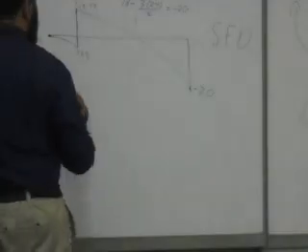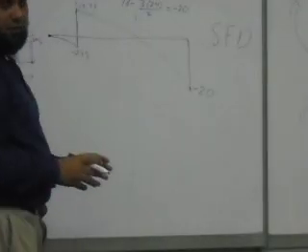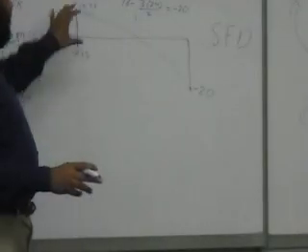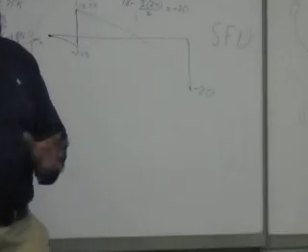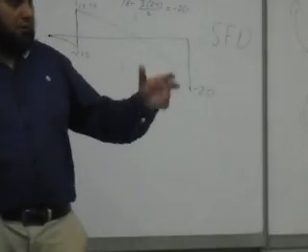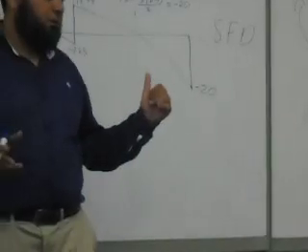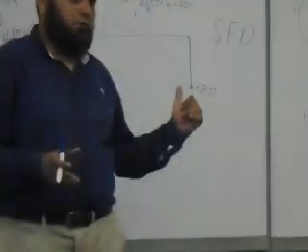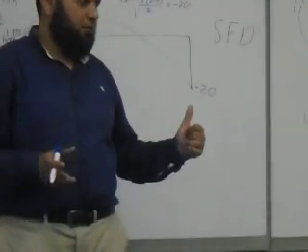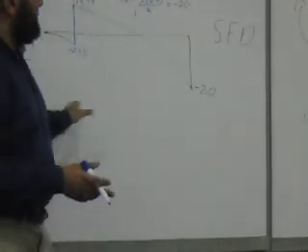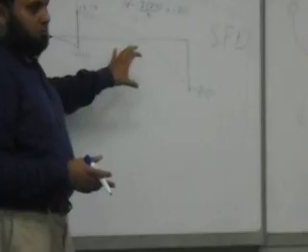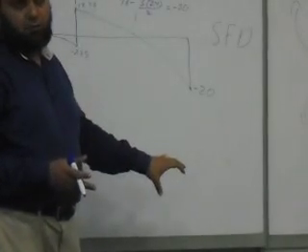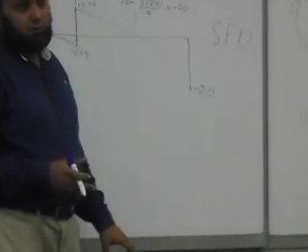But what makes a real difference for me in the shear force diagram is the values, the maximum values, because when you go and design, you will be designing based on the maximum values. You should not get it wrong. All these jumps, the maximum value, then different values. This is 10, this makes it 20, important. This 13.75 is very important. This 2.25, these values are important. We haven't taken a section after it yet.